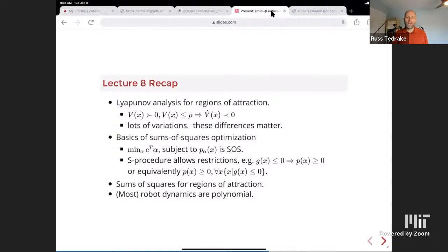If you were to solve for a control Lyapunov function offline or provide one, then you just have a job at runtime of finding some controller that is going downhill. That tends to be a much easier problem. There's no long-term look ahead. You just say, find me instantaneously some vector that goes downhill. Okay, thanks. These are great. Yeah, good questions. It's even better when I can hear them.